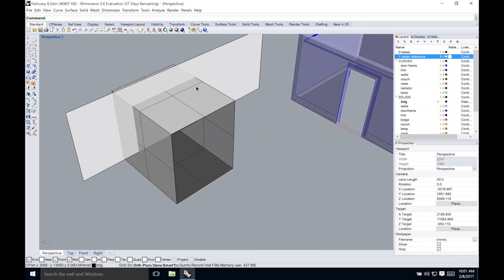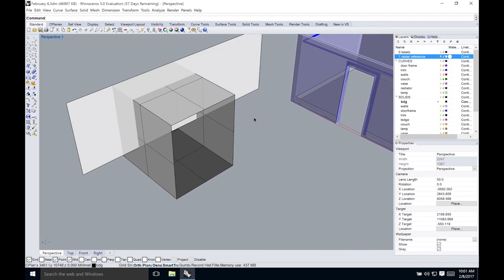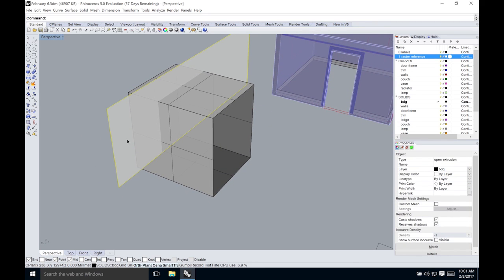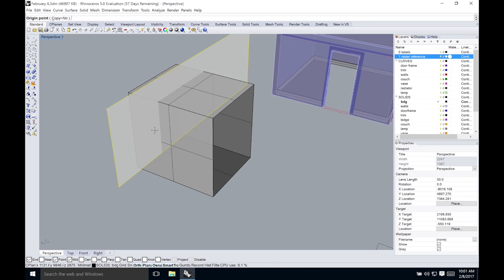So you can see when they are intersecting, and actually I'm going to scale it so it goes through the whole box. For that, there are 3 different scale commands. They each work in 1, 2, or 3 dimensions. So if I use the scale 1D command, and I can do this in perspective view, basically I'm able to adjust this surface only along one axis.